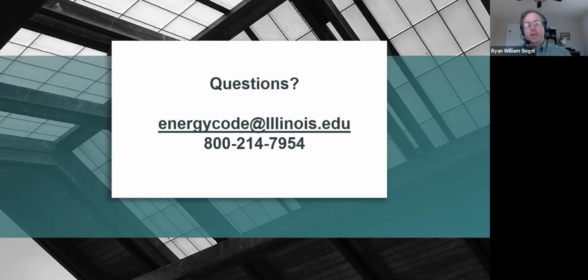Looks like we also have another question about lighting housings and why they are not insulated. That is a product standard, and so part of that is just how they manufacture those. They are not designed for insulation. However, that's where the code has come in and said those do need to be insulation contact rated, such that you have the ability and capability to insulate around those housings.